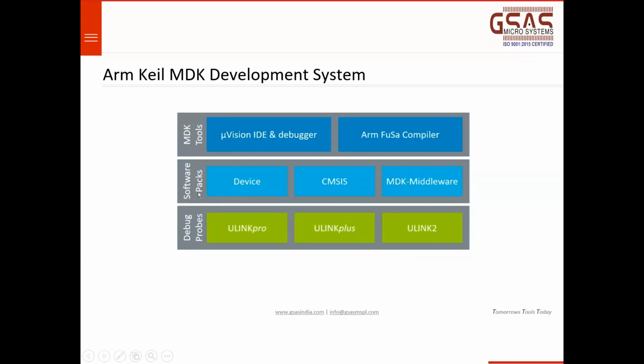With the help of pack installer, you can install the required software packs. So what are these software packs? You are developing a project based on a specific MCU, so you need device specific information. When you're developing software, you have to program the peripherals of a microcontroller. For that, we initialize those specific peripherals using the peripheral specific registers. And to access these registers, we need the device specific header file.